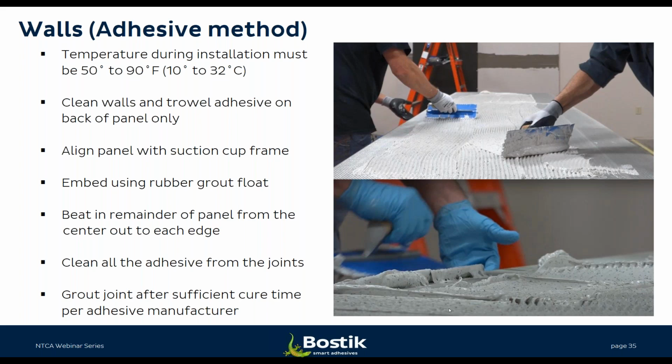So this particular type of adhesive provides a variety of different benefits. As you can somewhat see in the image, it's a highly fluid type of elastomeric type material, which ends up providing great coverage on the back of panels and is easily alignable after the suction cup panel frame places a panel on a wall. So the adjustability of this type of material is really, really great, offering more than 30 minutes of adjustability and anywhere north of an hour of open time in some cases, really at minimal around 15 to 30 minutes of open time.